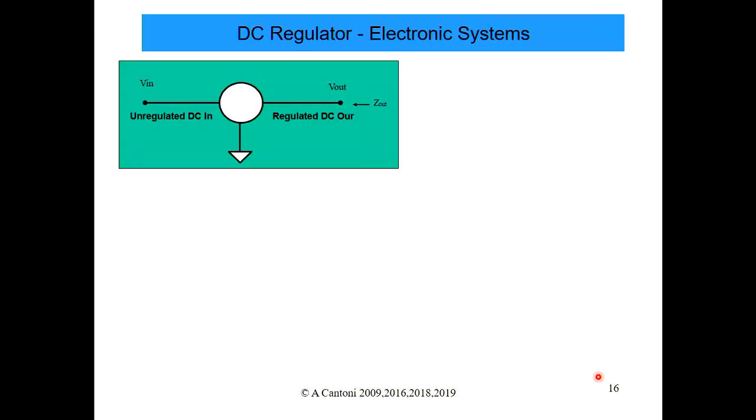But in most cases, like for this computer where we connect it up to the mains, you often have a voltage regulator. From the 240 volts you might have a transformer that steps down to something like 10 or 5 or 15 volts, and that gets rectified, and you have some noisy, uncertain, unregulated DC-like voltage coming in, and you want to produce a well-controlled, regulated DC voltage out.